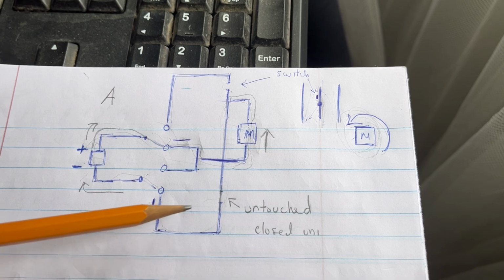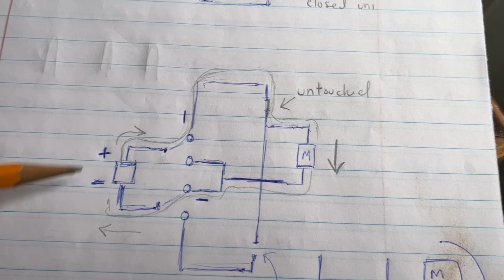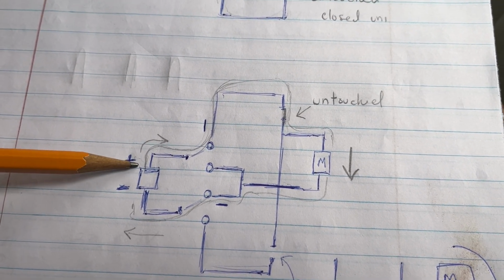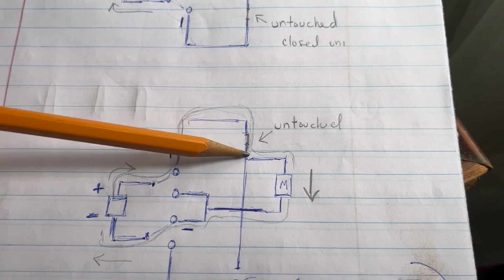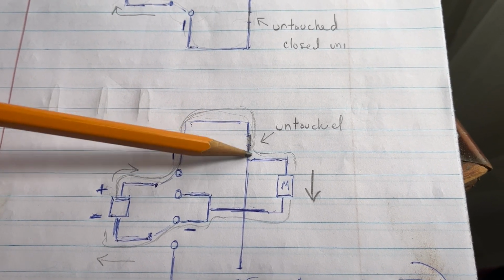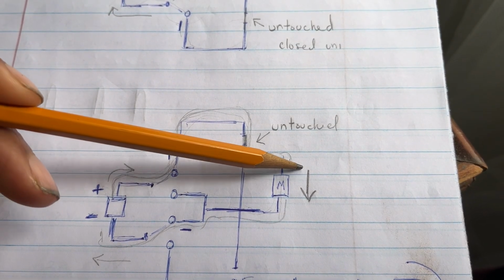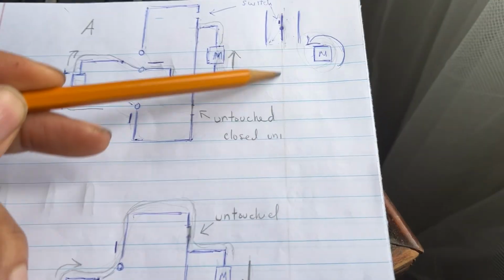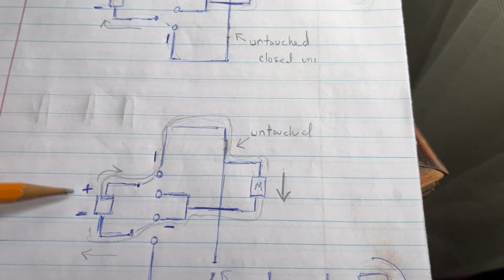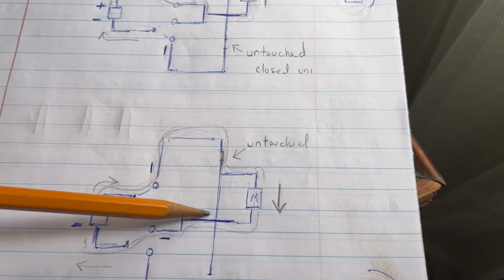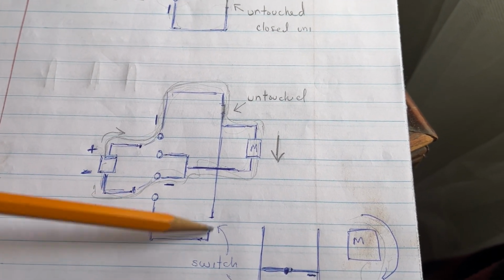With the motor going like that. All right, simple. So when you throw the switch the other way, right, the current takes this path, right? Now notice this limit switch is closed now, right? It takes this path, it goes around, and it should cause the motor to run in the opposite direction. Remember, counterclockwise, clockwise. So it's taking this path through the motor, and boom, that's the circuit. And that switch is open, so it won't go here.